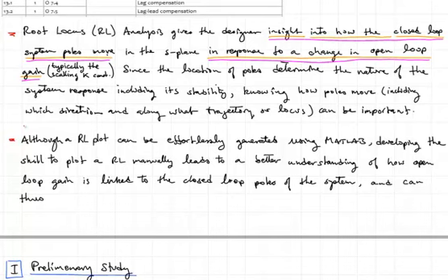Think of a servo system with perhaps just a proportional controller, constant K or Kp. We found that the damping ratio, zeta, was a function of that constant. So changing that constant results in the closed loop poles of the system moving.